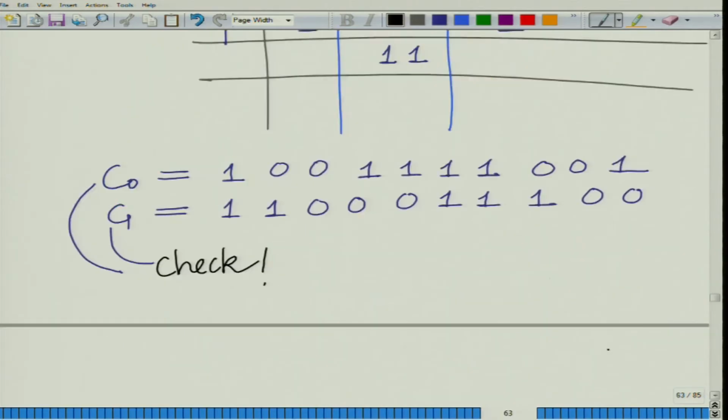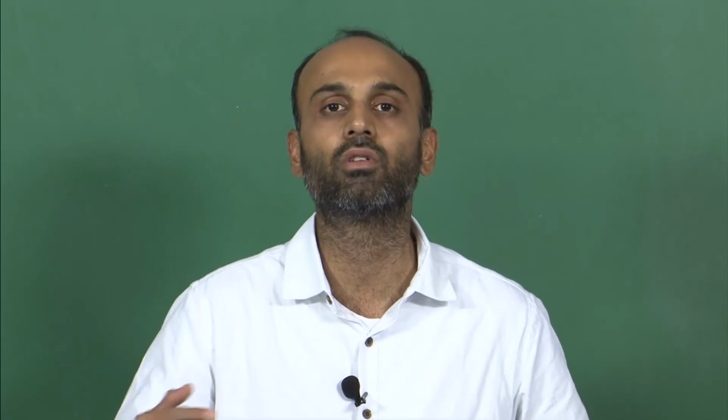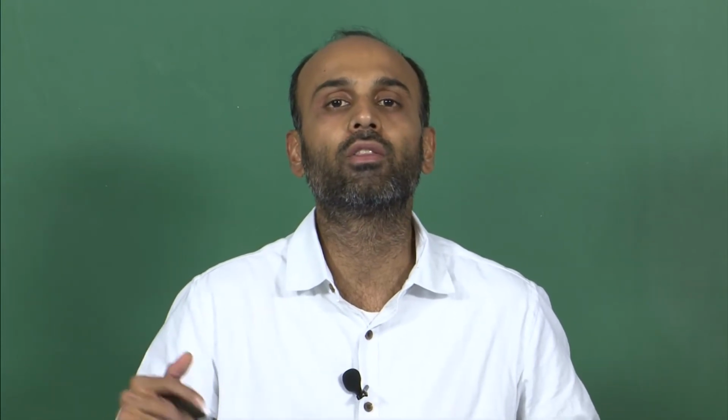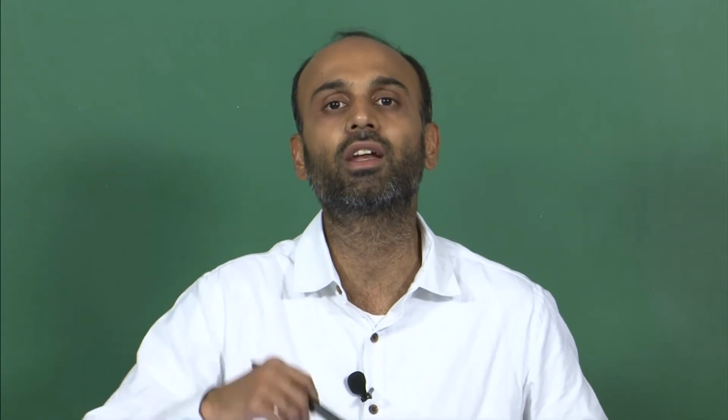But this is much simpler, correct, than doing the binary field operations at every time instant, considering xj plus xj minus 1 plus xj minus 2, and so on. By looking at the state transition diagram, one can store it in the memory of a computer and very rapidly generate the coded bits by simply looking at the initial state and the input bit, transitioning to the next state.